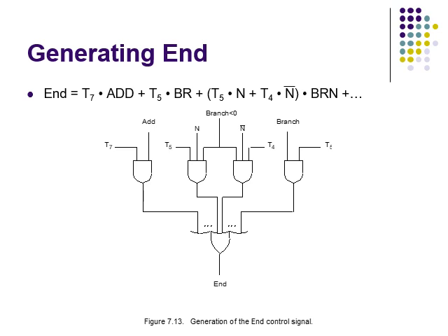The sequence of operations carried out by this machine is determined by the wiring of the logic elements, hence the name hardwired. A controller that uses this approach can operate at high speed. However, it has little flexibility, and the complexity of the instruction set it can implement is limited.